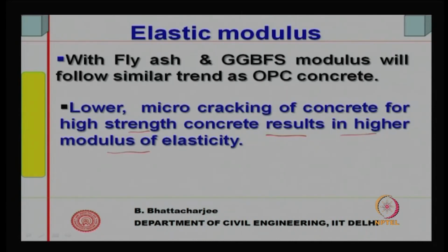what you are doing is, you are essentially reducing down the pores in the system. We shall see that when we discuss high strength concrete systems. You are reducing down the pores in the system. The pores are the ones which are the weakness or flaw in the material, and cracks initiate from such flaws.